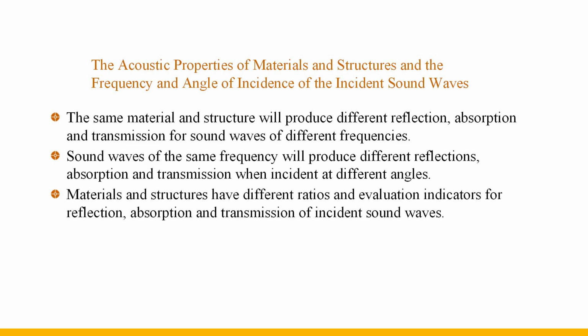The average sound absorption coefficient is equal to the total sound absorption of the room divided by the total room interface area. Since it is difficult to determine the area of people and objects in the sound field, the sound absorption of a single person or object is often used without the sound absorption coefficient.